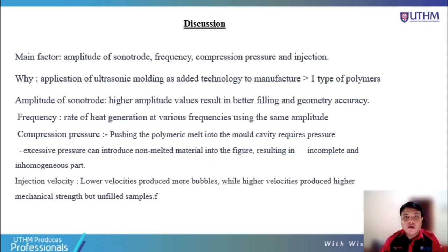Although there is no clear experimental relationship between ultrasonic molding parameters and the evolution of temperature during the process, a recent study with a sensorized mold shows that the higher plunger velocities have less dispersion in temperature values obtained from the infrared sensor placed in the mold cavity.